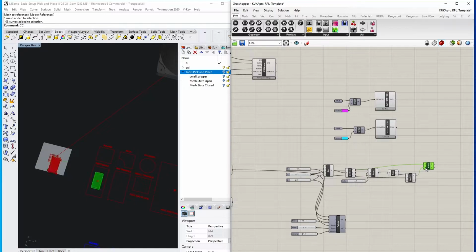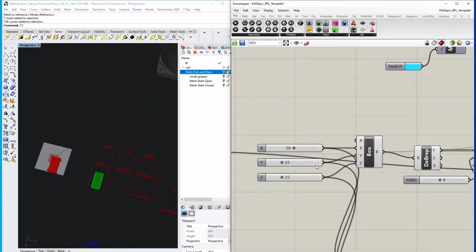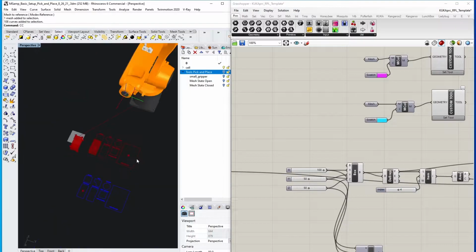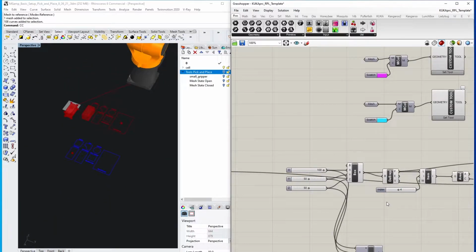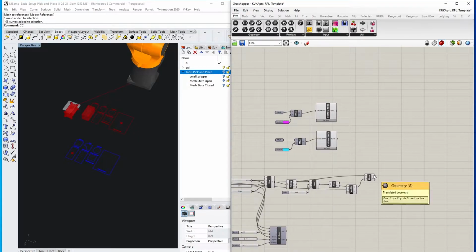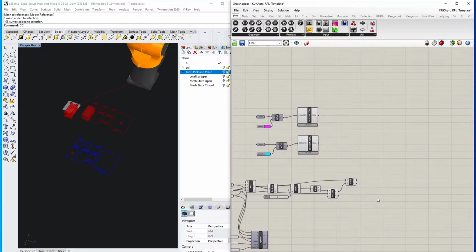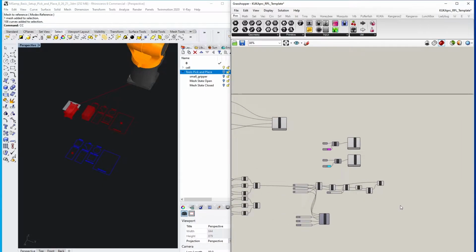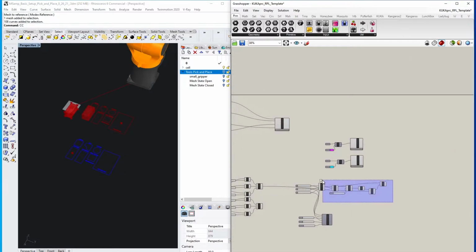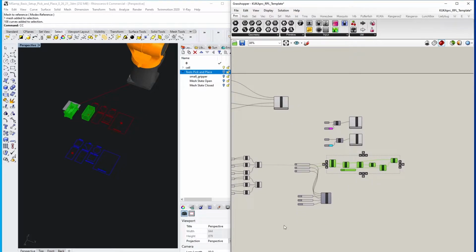using this vector. Now I see that our box is too small. It's about 1/2 as small, so make it 100, 50, 50 tall. And now we have an equally sized brick or rectangle that we can now change and manipulate parametrically. From here, we can leave it alone for now and move on to our placement object.